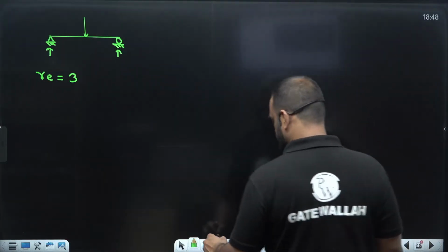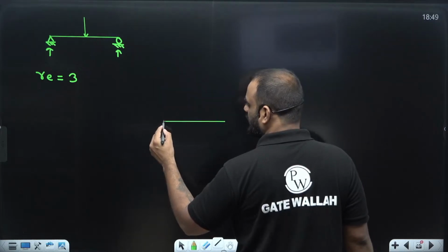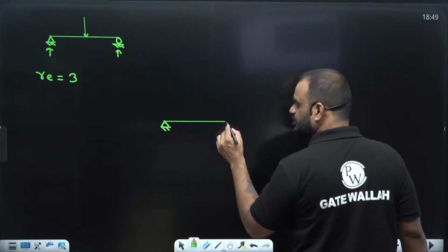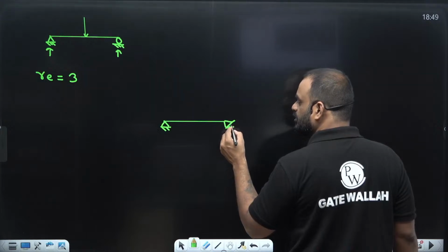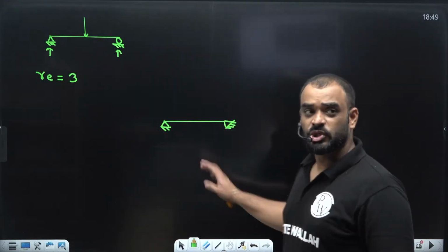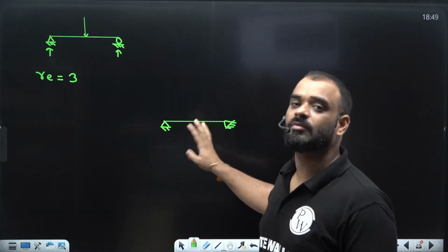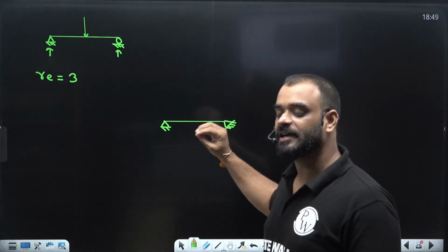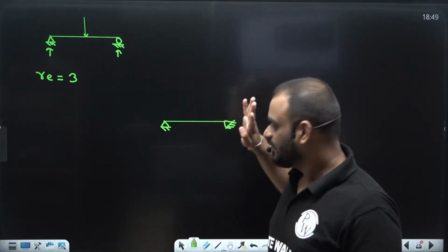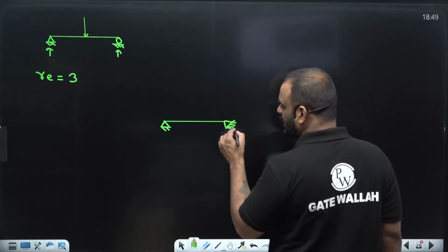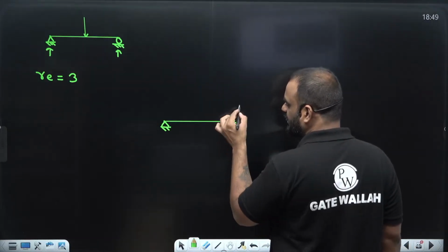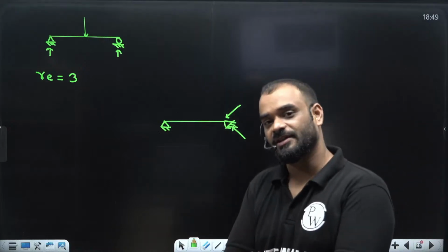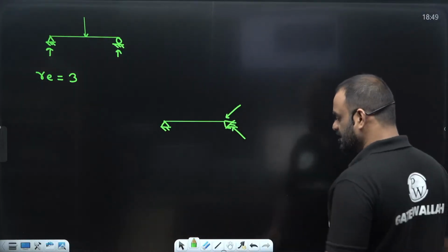Okay, Bhanu. Like this. So in this particular case, the total number of independent external support reactions is 4. Right? It is 4, because you know that this is our reaction which is unknown, and this one is another reaction which is unknown. So in this case it is 4, not 3.